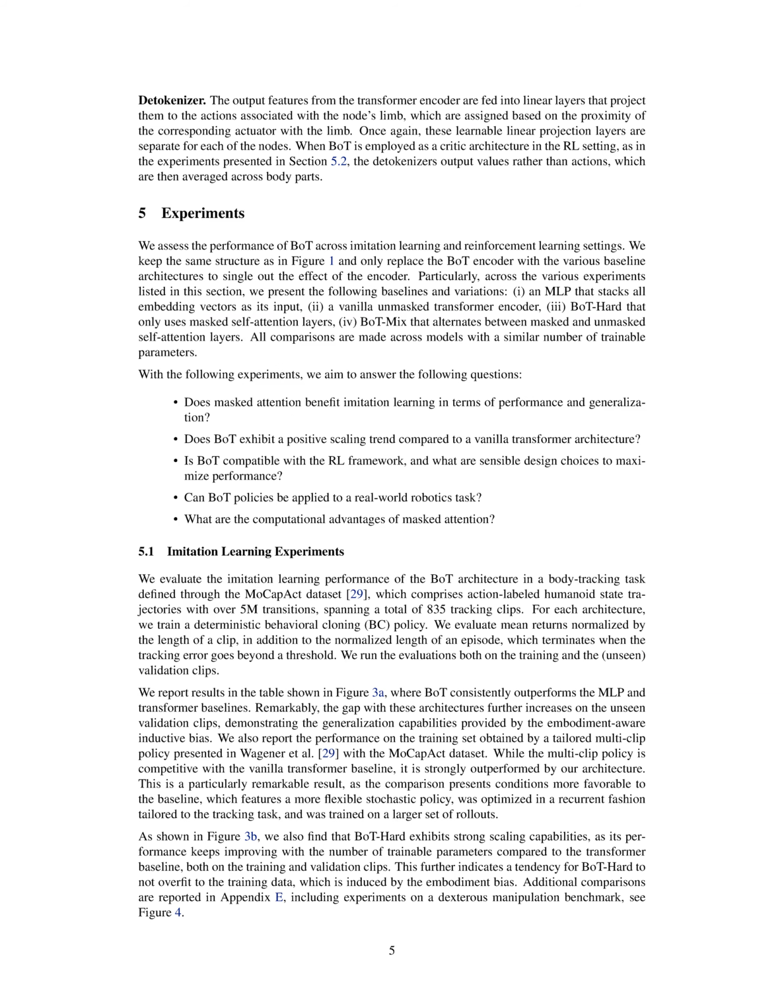Finally, a detokenizer converts the output features back into actions or values, ensuring that each node's output is tailored to its corresponding actuator, thereby enhancing the overall performance and generalization of the robot's learning policies.